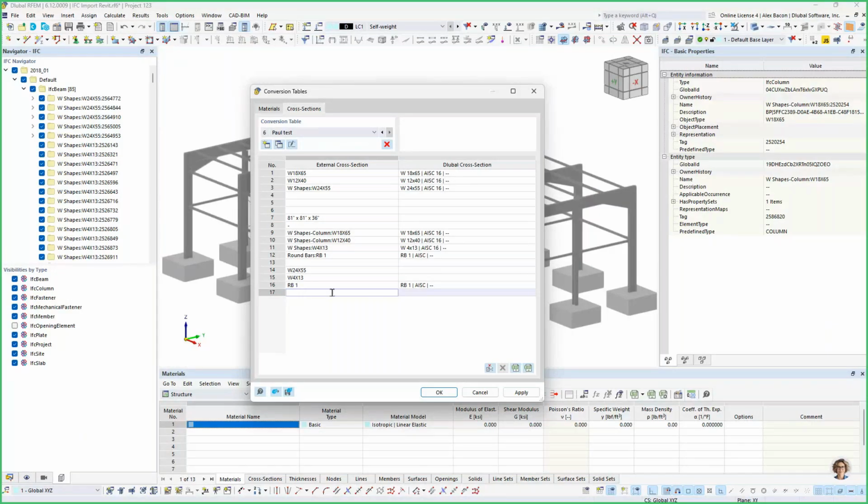With this cell here, you can simply use this graphical button to select the section or material name within the IFC properties. You can type it in manually. You can create an XML file and save the XML file and share that with colleagues. And you only have to do this once. So it's really quite simple to set up.